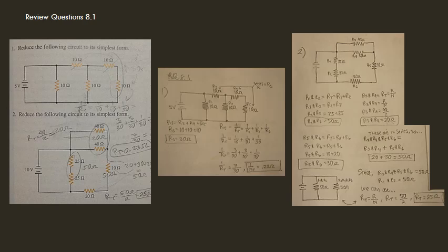That is a parallel circuit. If you see resistor 5 and resistor 6, those two are in series, as well as R1 and R2. Those are also in series. So there's a number of ways you can go about solving for this circuit, and we're just looking to simplify it as much as possible.